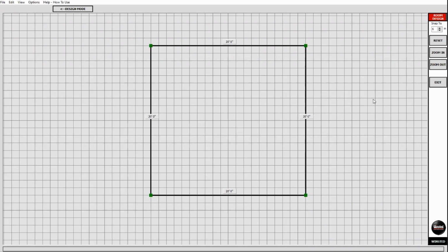view. In order to set the dimensions, the Snap tool can be changed to anything. I usually change it to 1 so I can get within 0.1 inch of the actual room. Then the green boxes: here's how you're going to move the wall to increase or decrease the wall size. You can also add other ones. If you click anywhere on a black line, this is very helpful.